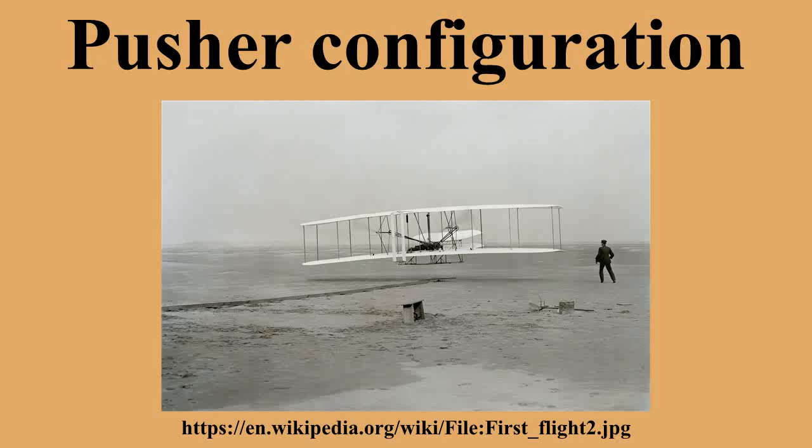In a craft with a pusher configuration, the propeller is mounted behind the respective engine. According to British aviation author Bill Gunston, a pusher propeller is one mounted behind the engine, so that the drive shaft is in compression. Pusher configuration describes this specific thrust device attached to a craft, either aerostat or aerodyne or others types such as hovercraft, airboat and propeller-driven snowmobiles.